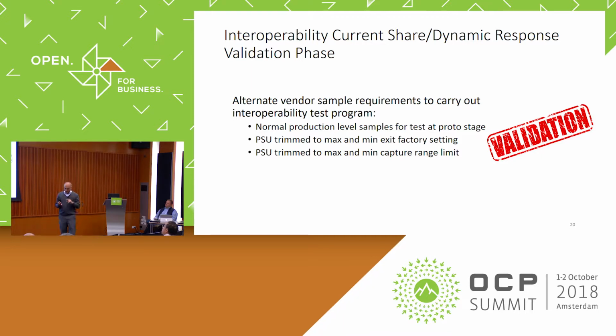So, if you can appreciate, there is a multiple amount of test cases. In this case, we do various load changes from, let's say, 10% to 90%, 20 to 80, different input voltages, different line conditions, different load conditions. So a typical Interop test report can go up to 1,000 pages if you look at all those test cases. So it's pretty extensive.